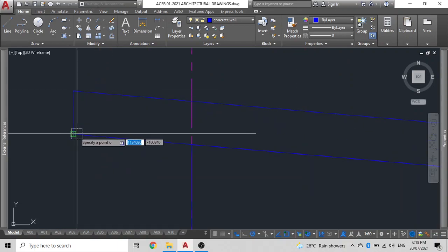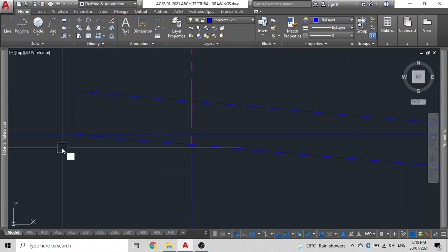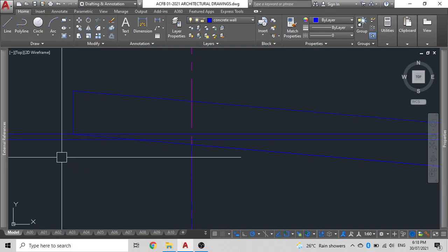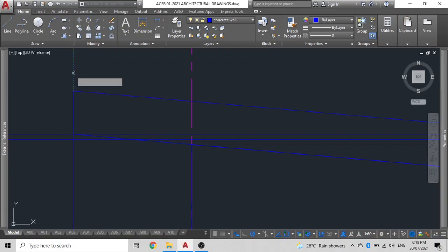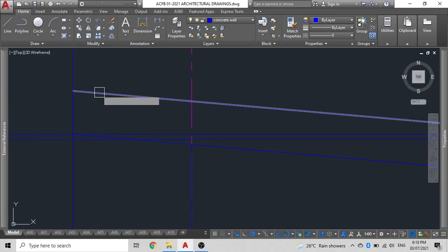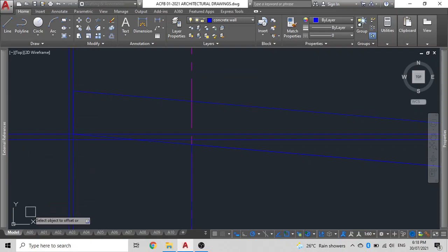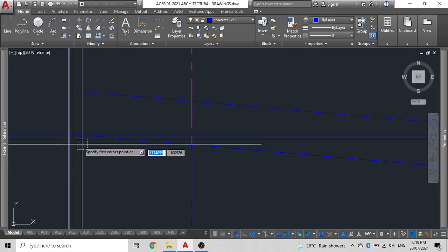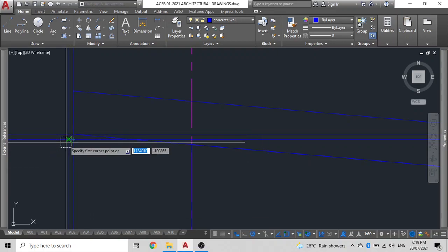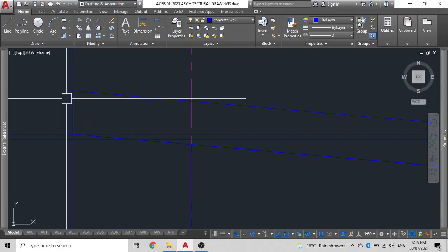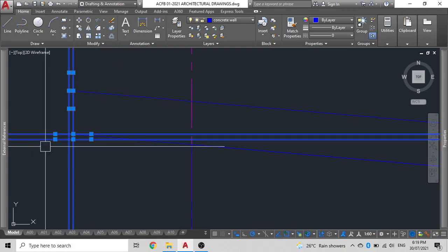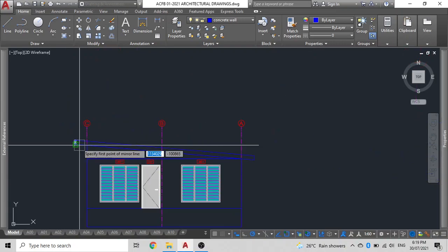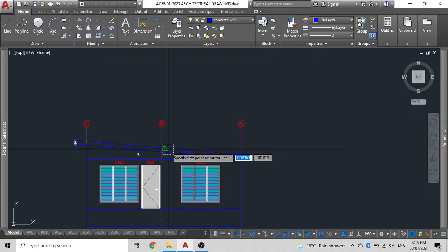And the next thing that I like to do is I like to just create the roof as it should be. So I'll draw an X line over here. Then I'll offset it by 25 mm. Then I'll draw another X line like so, and offset that by 20 mm. Then I type REC for rectangle. Press enter. Snap to that corner and then go up diagonally. Select these 2 lines and delete them. And what I can do is simply mirror these guys so that they set it right into place.